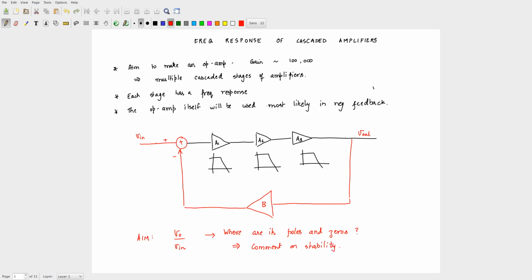And in the last class, we also had a typical kind of op amp configuration, where the B network became very clear, and that op amp configuration was the non-inverting op amp configuration. So in the non-inverting configuration, I have my V in given directly to the positive terminal of the op amp.